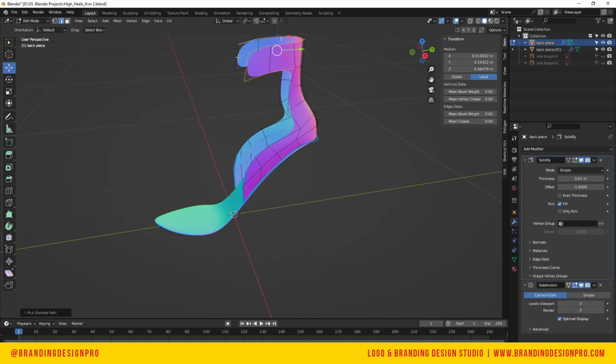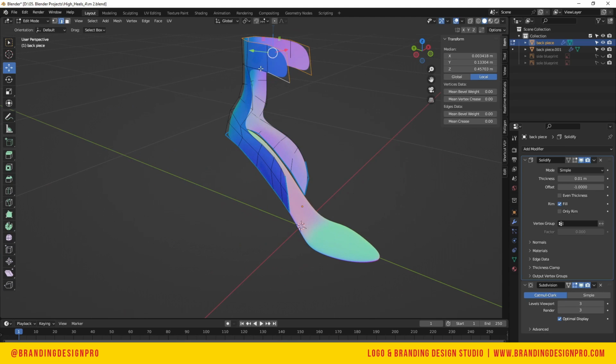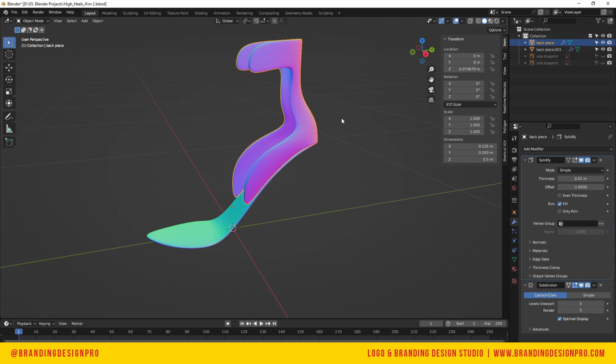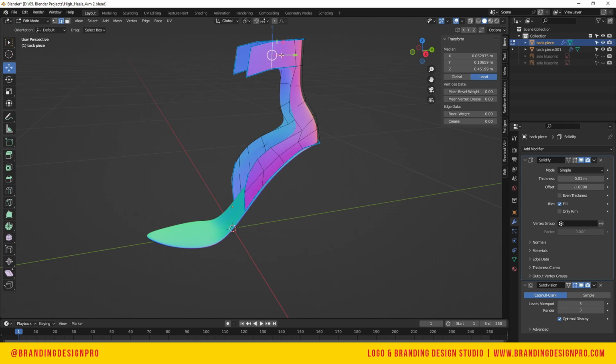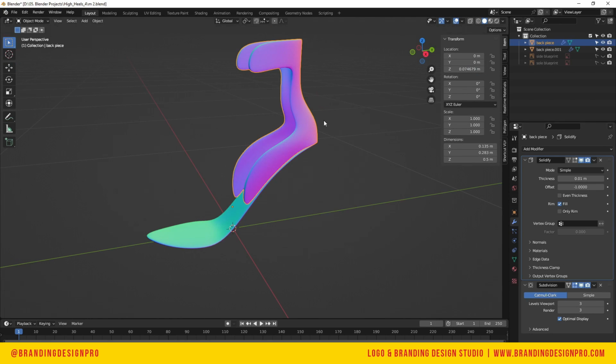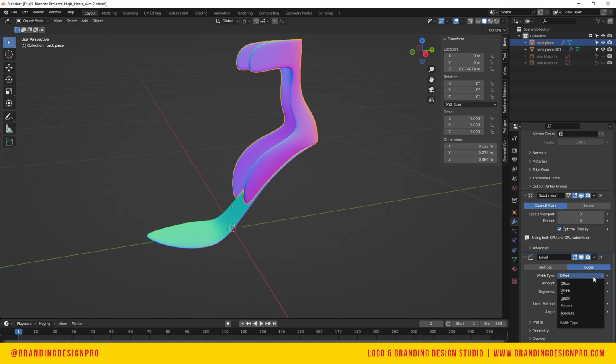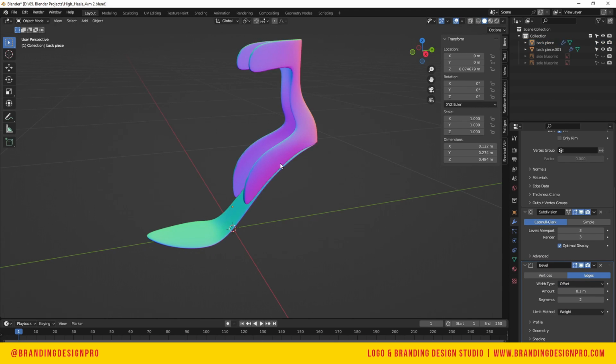Sometimes working with the edge details or edge beveling, it could create certain artifacts. The best option ends up being that we actually need to add some dimension to the shape and then bevel it, but just gonna go ahead and, let's see, let's hide the subdivision, bring in solidify. And if we take the bevel and change the weight, increase the segments, nothing really happens.